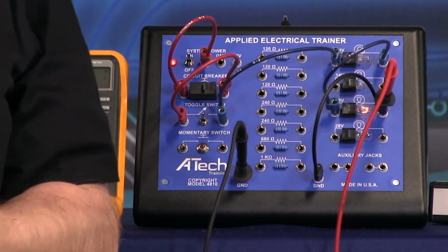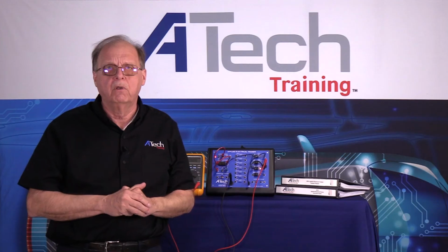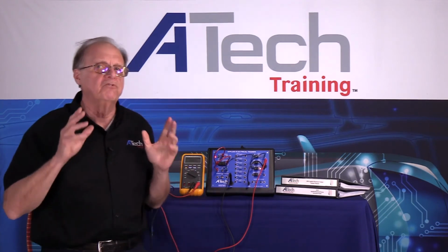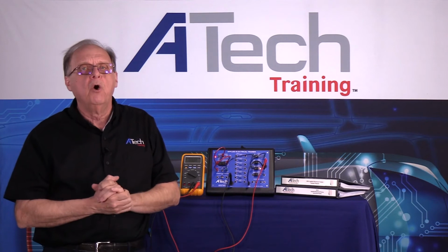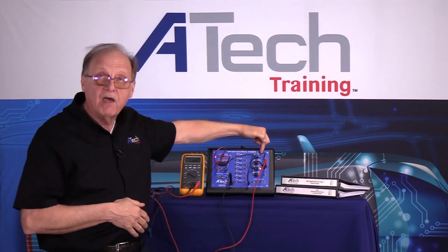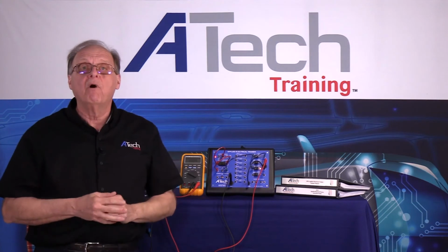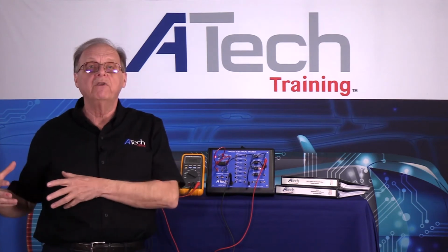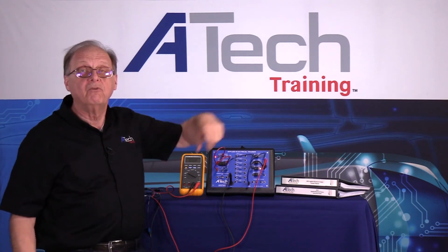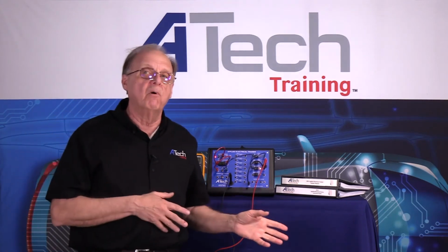Some of you instructors old enough will probably remember the Quad 4 on General Motors. They had some bulletins out, if you go back and check, that told you when you're checking the injectors on the Quad 4, one injector would pull all the energy, just like this just did here. The problem was one injector would shut down, just like the light just did here, because the one was using all the energy in the circuit. So in other words, you have to understand you should do voltage drop on both components.